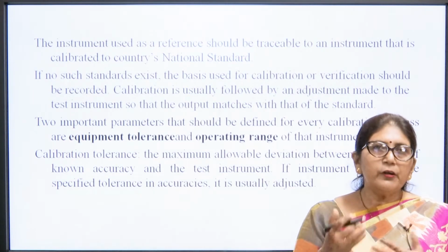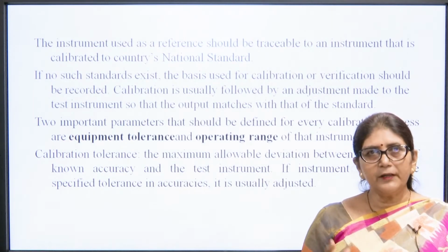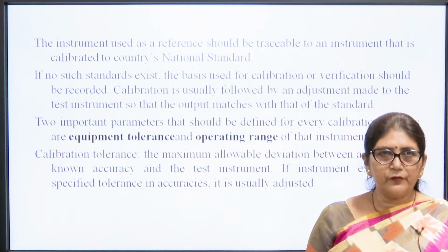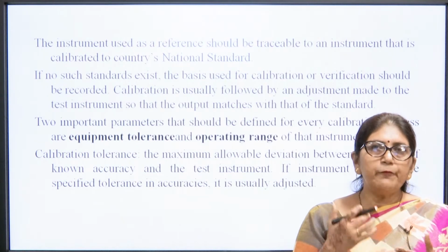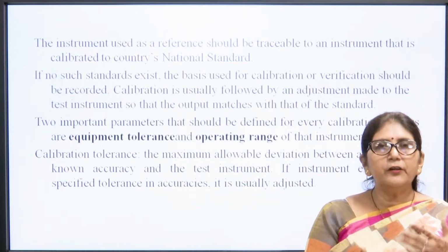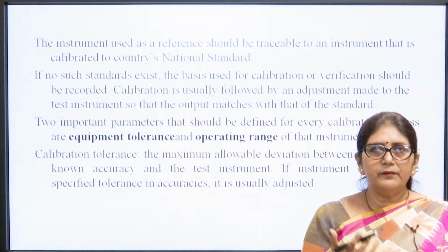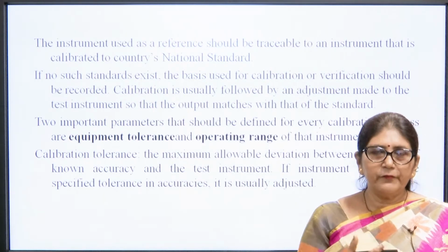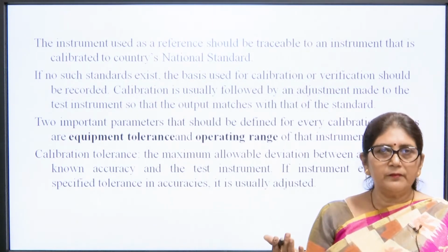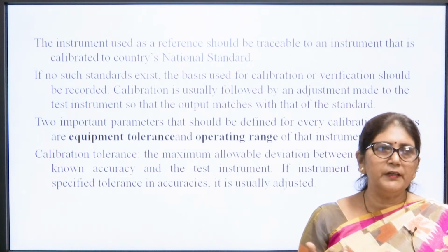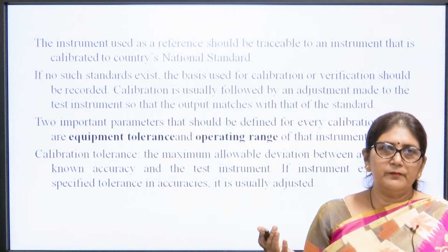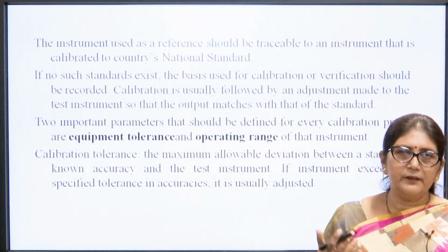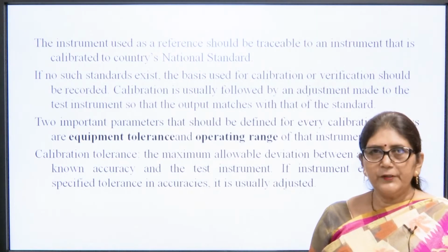voltmeters, and periodically we will send them to the country's national standard laboratory. Because in every measurement or calibration, the national laboratory will charge some fees, and if we send all the 100 meters to the national laboratory, then the charges are more. And the second thing is that there is loss of production when the instrument goes for calibration.